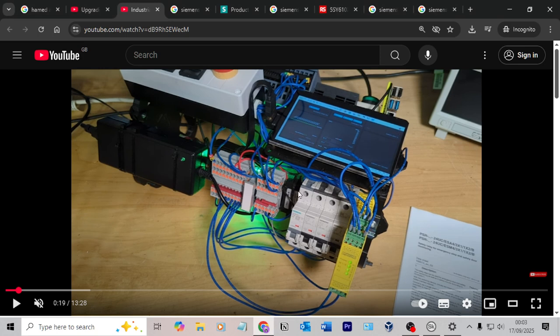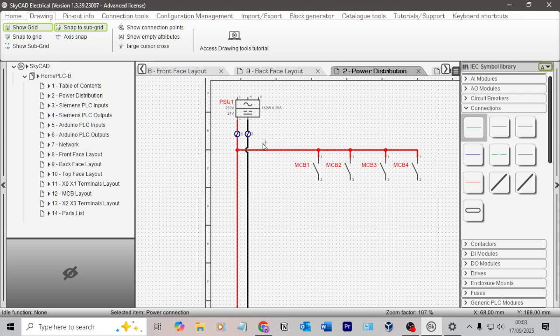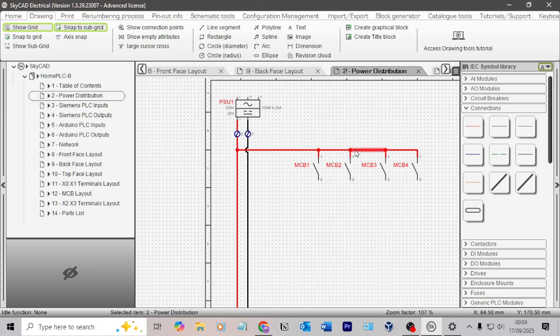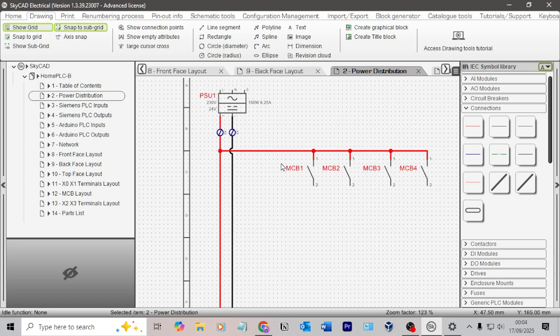Normally in a panel you've got the jumper bars that just get inserted in, and it's basically a bus bar. They slide in, and they're a very efficient, very good way of wiring up a whole bunch of MCBs. Just right along the top, jumper bar in, you're done, all of them connected. I don't have a jumper bar, so I could double crimp and jump over. I don't have any double crimps, I'd have to buy some. So I think I will just run 4 individual wires. It does give me some leeway if I ever wanted to remove one. So running 4 individual wires, how do I want to draw that?